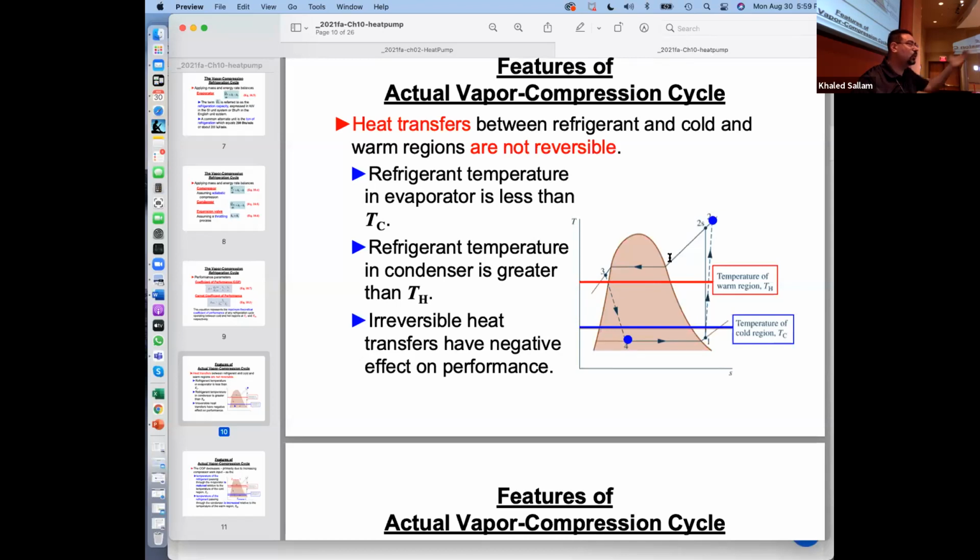The fact that your unit that you made for us is going up even higher, that's on the manufacturer, not on the environment. Carnot wouldn't need the delta T. Carnot would be just on the T_H, ideal. It actually transfers heat without any temperature difference, and it compresses isentropically too. I mean, imagine that, right?